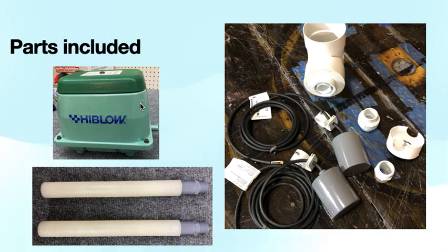So here are some of these parts that I was talking about that are included. This isn't all of them, but this is some. We're using an 80-liter high-blow pump along with the diffusers. We're providing those. The diffusers will actually already have Teflon tape on them, and so those will just be screwed in to the configuration for the diffusers in that first tank. Again, here are the floats, already pre-tethered. No need to adjust the tether that we have on those. That's how we want them. And those are the brackets, and that will just slide onto a 1-inch PVC and be able to be drilled in. The screws are already pre-drilled right in there.